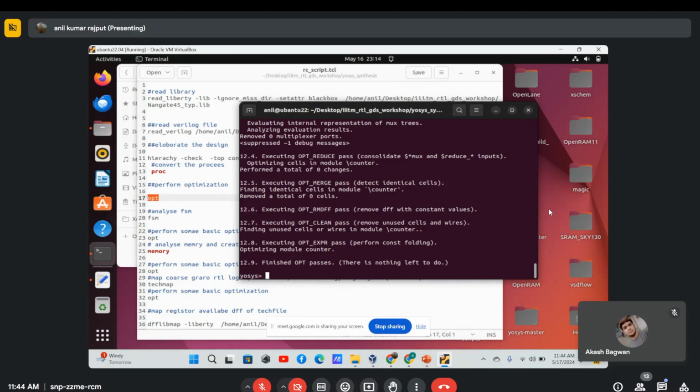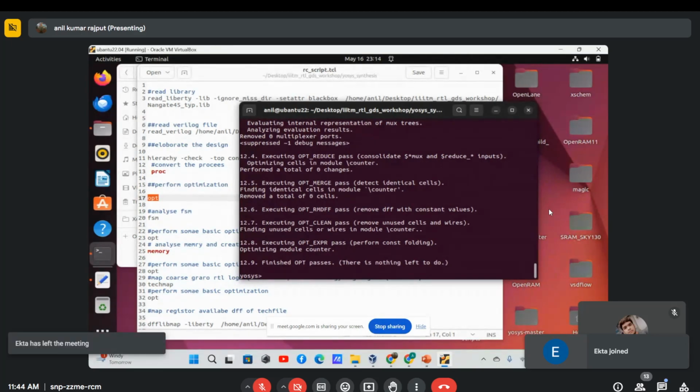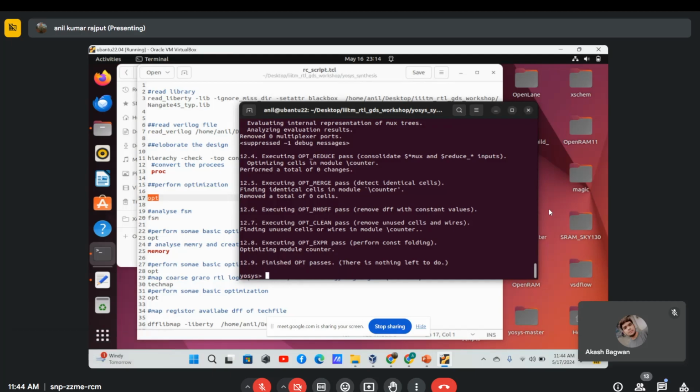Like that, if there is a lot of code, they use different logic gates to design your RTL, but some of the gates are not required. So during the optimization, they just remove those gates and optimize your RTL. Optimize in terms of your area and in terms of your timing and delays. If you reduce one gate, the delay is drastically reduced. For that, there is some optimization.